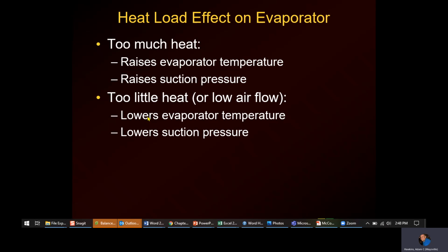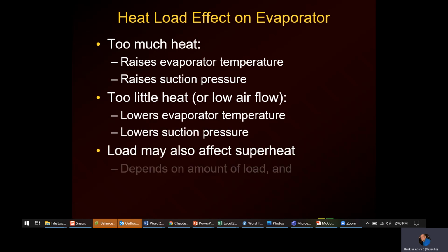Too little heat, low load, is going to lower your evaporator temperature. In our lab, a lot of times we're dealing with low load situations, and it lowers our pressures to where we're running more like 38 and 37 instead of 40 to 45. So just the nature of the beast. And it also affects your head pressures as well.